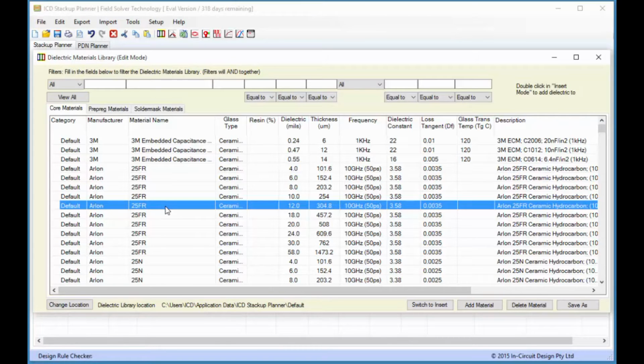Because obviously there's FR4, which has been the standard material for many, many years, but in high-speed design we need something with a better dielectric constant. But usually when we pick other materials with better dielectric constants, there's something we have to sacrifice as a result of that. So we have to be very careful about the ones that we pick. And this tool really is more so that you can have an intelligent conversation with your fabricator at the beginning of the layout. This is not something you want to present to them at the end of the layout and hope that it will work, because you're going to put both yourself and the fabricator at great risk in terms of accomplishing what you're trying to do.